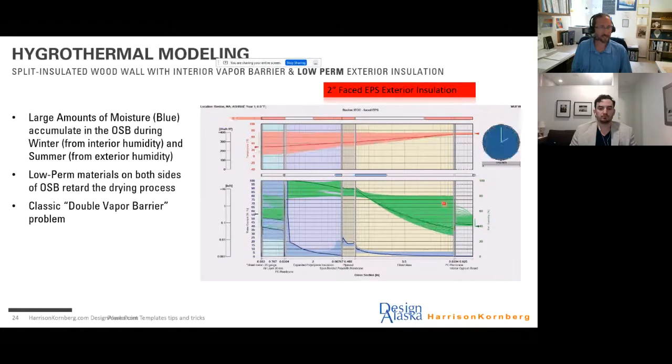And you can see it's pretty dramatic, the change. Of course, this is sped up. This is very fast motion animation, but the conditions change in that relative humidity of all the building materials. And based on the material properties of the vapor permeance, of thermal conductivity, how those properties change with both temperature and relative humidity, it's calculating all of that for each element for every hour for this model that I ran spanning 10 years.